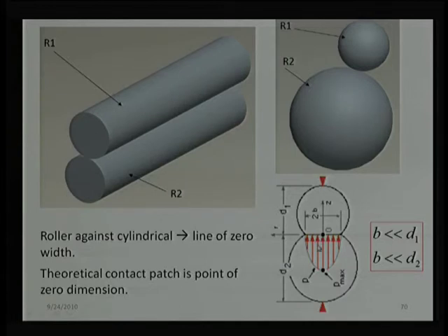It is not even matchable, not comparable, not even 1% of this; it will be much lesser than this. We say that this kind of deformation is very localized, particularly when there is a convex geometry. If there is a non-convex or concave geometry, then deformation will be more, but pressure generation will not be that high. In this case the deformation is low, or the extent of the deformed zone is low, but maximum pressure will be very high, and this max pressure can go even to gigapascals.